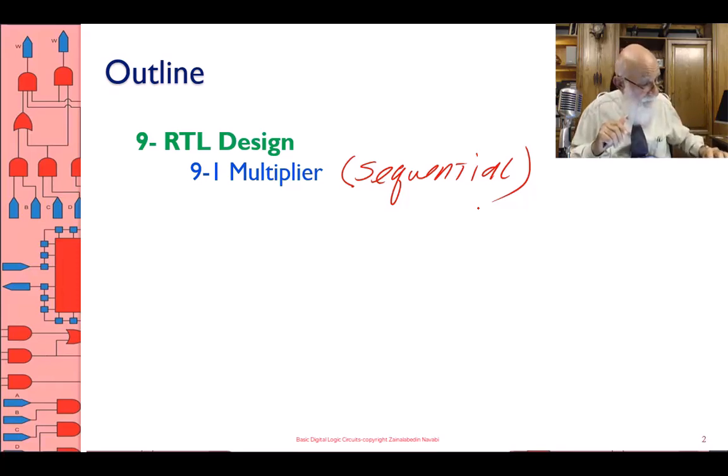Okay, I can do a multiplication by a very good shift and add algorithm that is usually done, or do a Booth algorithm multiplication, which is a signed number multiplication, which would require a lot less hardware than the combinational big multiplier, and also it requires fewer clock cycles. But then I don't want to do that first.